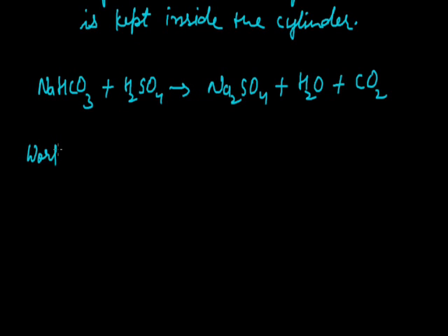If we talk about its working, the released CO2 gas formed inside the metallic cylinder exerts pressure and force, so water solution comes out through nozzle. The mixture of the liquid and CO2 extinguishes the fire. Here water helps in lowering the temperature of combustible substance below its ignition temperature, and CO2 helps by covering the burning substance. It cuts off air supply and fire is extinguished.